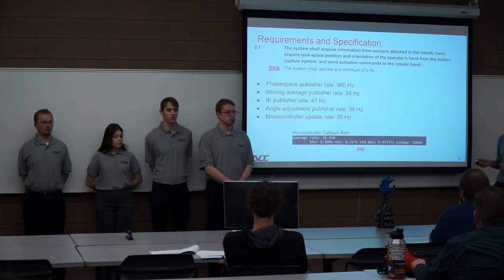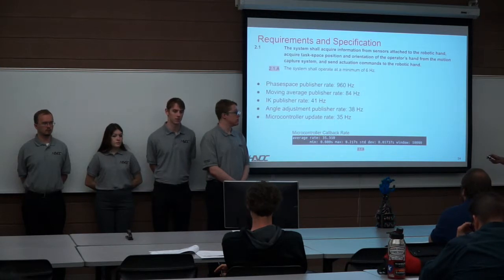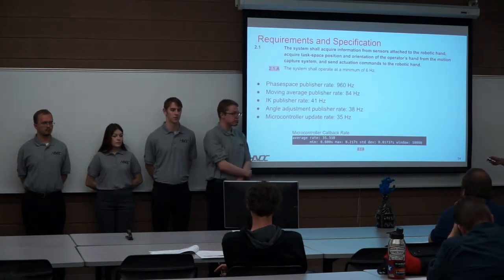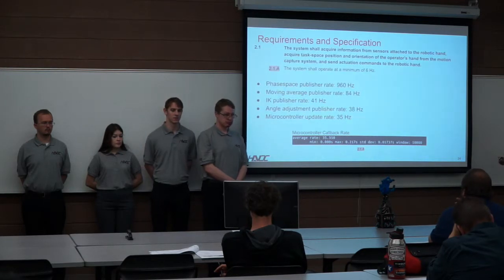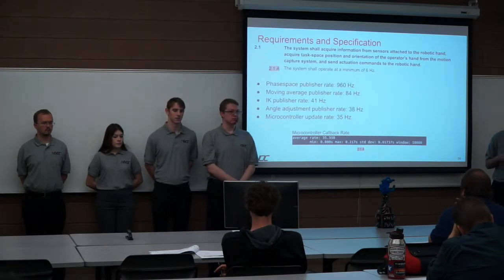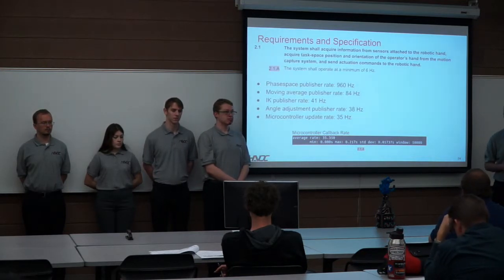Our PhaseSpace publisher publishes at 960 hertz. Our moving average publishes at 84 hertz. Our kinematics publishes at 41. Our angle adjustment publishes at 38, and then finally our microcontroller updates the servo values at 35 hertz. So this meets our specification.